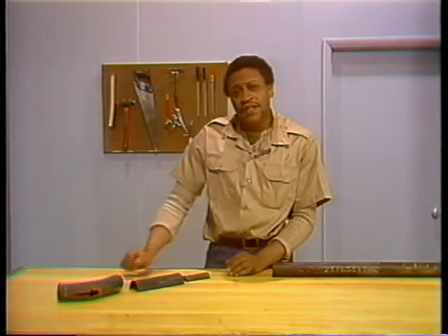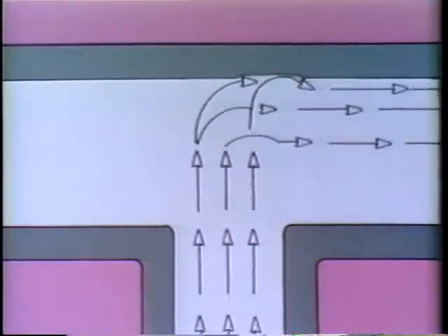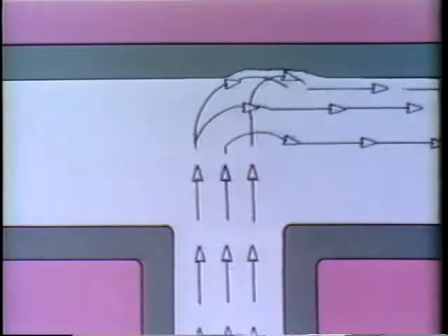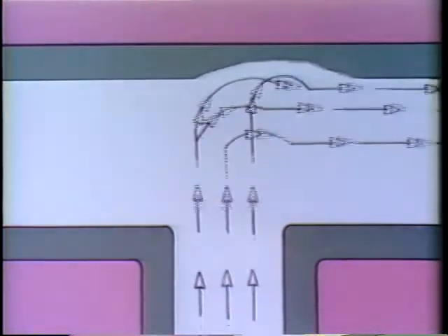Corrosive slag is still another cause of corrosion on the outside of the tube. Corrosive slag is formed by contaminants in the fuel. The next basic cause of tube failure is erosion. Erosion is the gradual wearing away of tube metal. This weakens the tube. It can occur on either the inside or the outside of the tube.